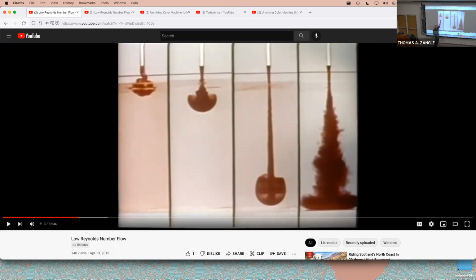So we're going to look at ultra low Reynolds number. We're going to take Reynolds number much less than 1. We typically write this, and we'll see it written in the next video this way, as Re much less than 1, with a double less-than sign, meaning much less than 1. In practice, this is Re less than about 0.1. That's what we mean by double less than. And we're going to look at the consequences of Reynolds number much less than 1.